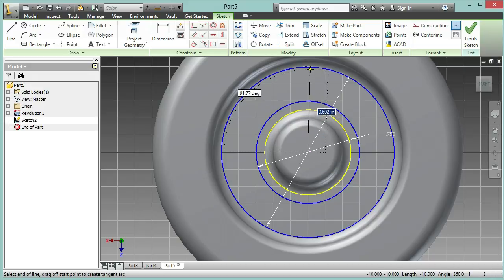So now I'll create a line and have it go up to the top right here, which would be 0.625, and I'll have an angle right here of 30 degrees, or sorry, 15 degrees, and then create another line, same length, and I'll have that at 30 degrees. Or sorry, 45 actually, that should be.